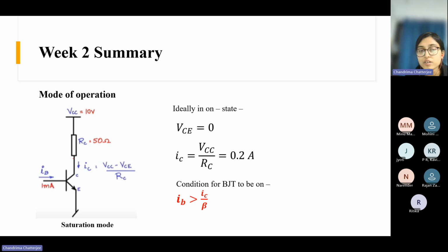When we want to complete the circuit, it should be in on condition. And when we want that no current should flow, then we want it in off condition, just like a switch. So whenever we want to use the BJT as a switch, the mode should be saturation mode, not linear mode. Please understand this.